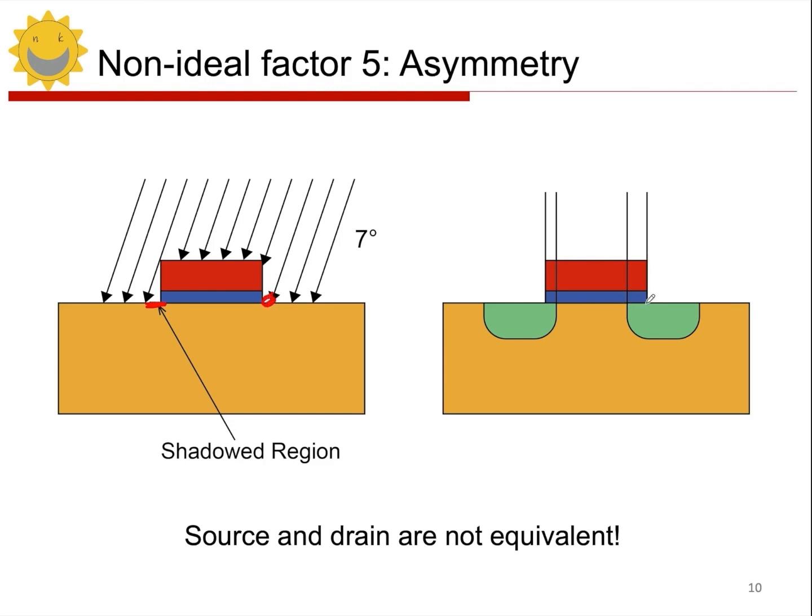So here, for example, the extension under the gate is larger, and on the left, because the edge of the gate is a shadow position, it cannot receive the implantation, right? So in this case, the overlap will be relatively small. Someone may ask, why is there overlap if there is no ion implantation here? What needs to be noted is that after the ions are implanted, they will diffuse. So even if they are implanted elsewhere, they will slowly diffuse under the gate. The distance of diffusion is quite limited, so the degree of overlap will definitely be smaller than on the right side.